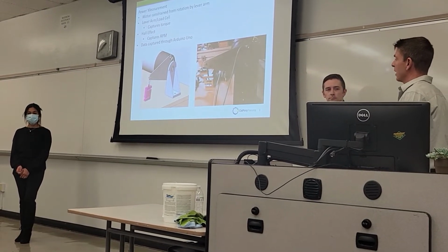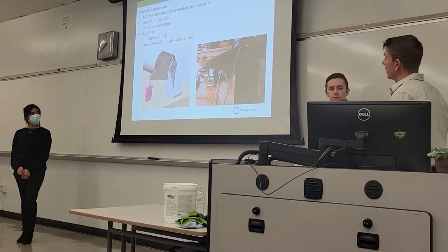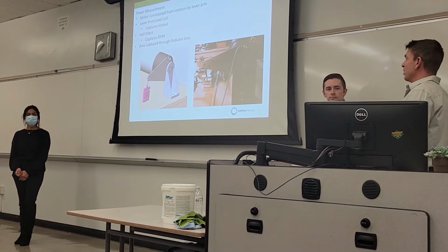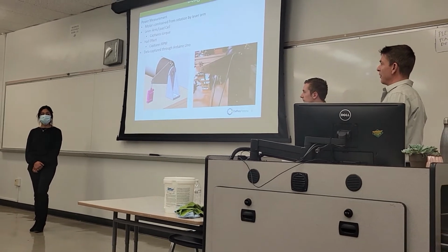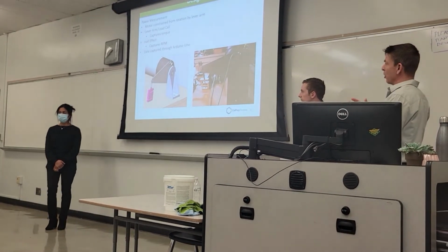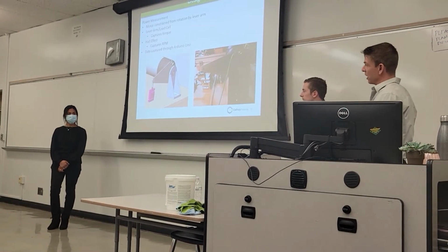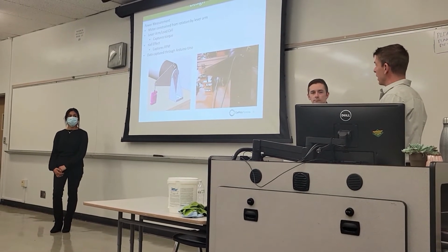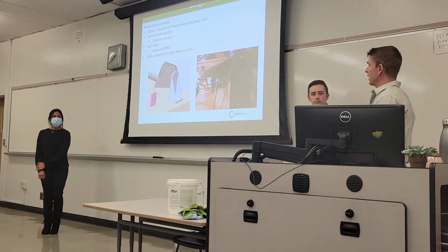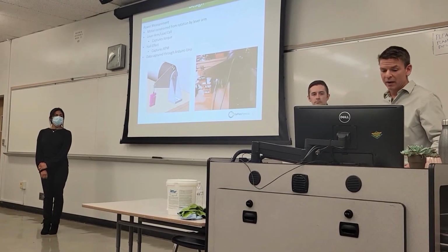The pink item on the picture on the left. It's basically a Newton's third law principle where the torque at the shaft is getting transferred back through the motor housing into the load cell. That's where we get our force times the distance of the lever arm, and then the Hall effect sensor is going to capture our RPMs, and we combine that for our power reading.